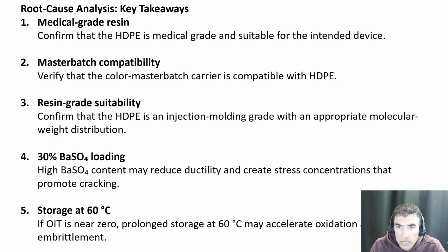A very important thing is the resin grade suitability. We found that the HDPE was extrusion grade and not suitable for injection molding grade. I mean, you can use it, but it's not the right resin for this. It has a high molecular weight distribution and is not intended for the injection molding process.